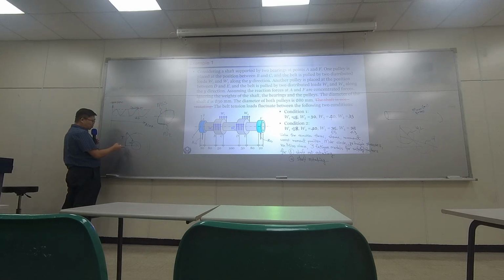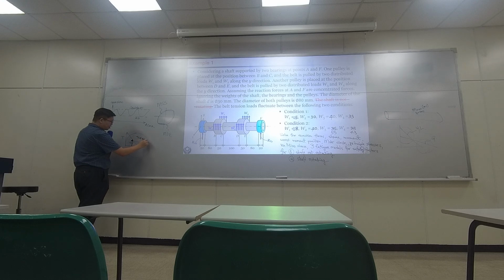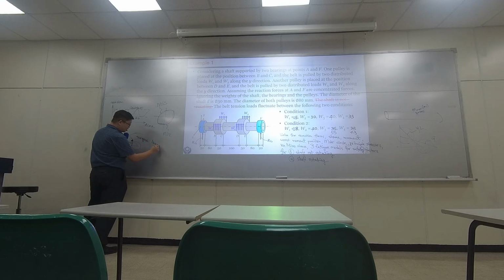Did you compute the torque of this one? I think so. Yeah. So please, when you compute the torque outside, you need to just assume torque is linearly distributed in shaft and pulley.